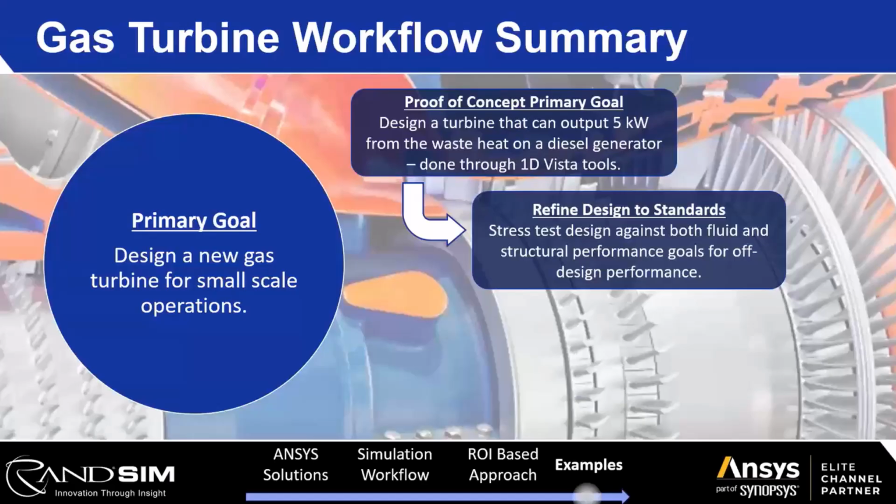So we might get into refining some of that. That could be looking at making sure that stresses within the blades that we're designing are satisfactory, and that from a fluid characteristic perspective, we're not having issues. Maybe we don't expect to have as much buildup of soot within the turbine, or we've got some mechanism we're starting to design for cleaning out that diesel exhaust before it moves through our turbine, right? It's starting to get into some of those auxiliary components to design.